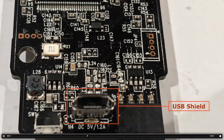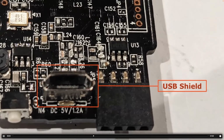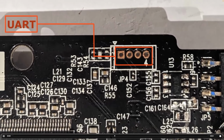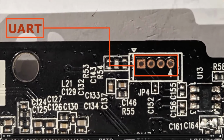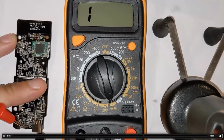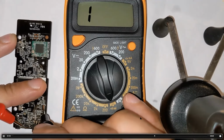Whenever we are measuring voltage, in this case, we want to find out the ground. So we want to have a reference ground, which could be any metallic shield on the device or any known ground. And then the other probe of the multimeter is what will iterate over all the different pins. So we'll go through all the pins, and wherever the multimeter produces a buzz sound is the ground of that chip, or the ground of that particular UART pin combination.